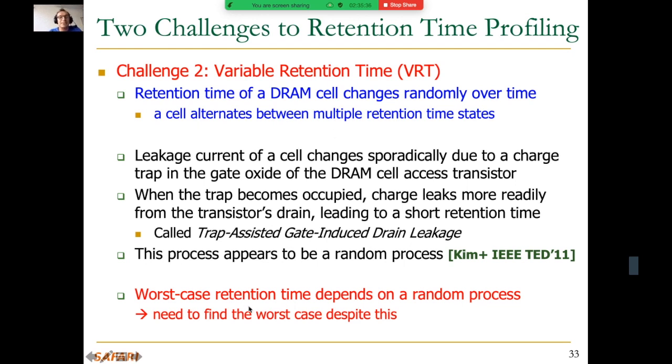Now let me give you another tidbit, even though we're running awfully late on time. You can say, okay, this problem is the DRAM manufacturer's problem, and they should figure out a way to solve it. You're partially right, but if you actually take a DRAM chip and solder it on a board or in a DIMM or a module, you're actually messing with the retention times. Why? When you're doing soldering, you're actually exposing at least parts of a DRAM chip to high temperatures. And those high temperatures actually change the DRAM retention time of different cells. And that doesn't sound very good.